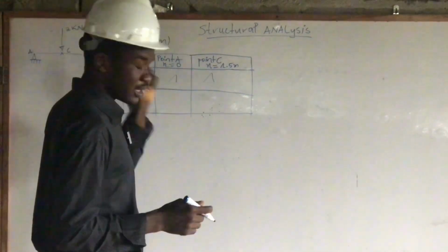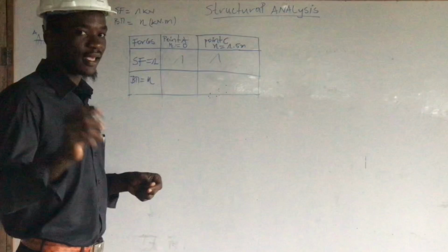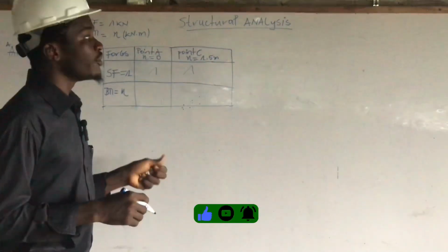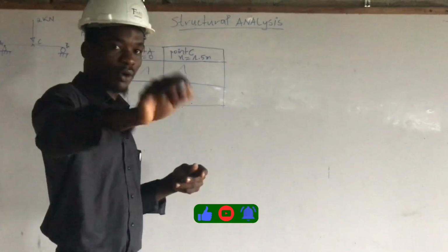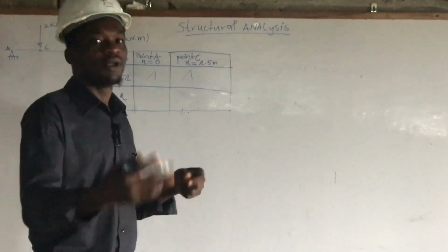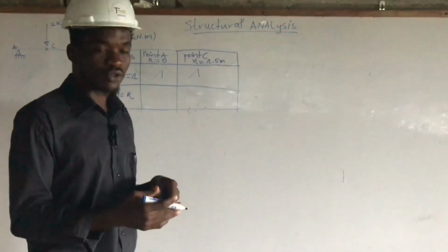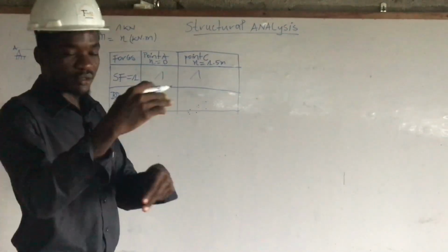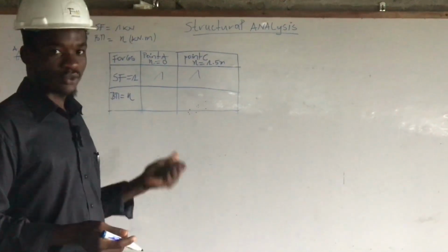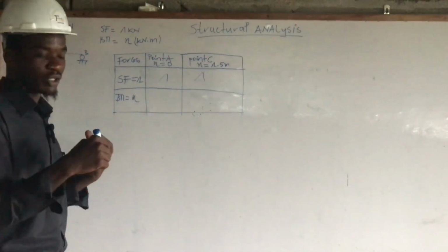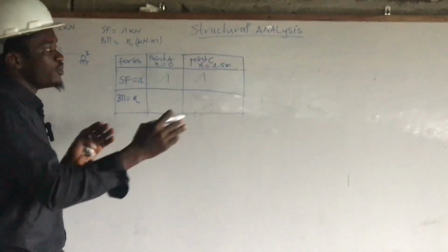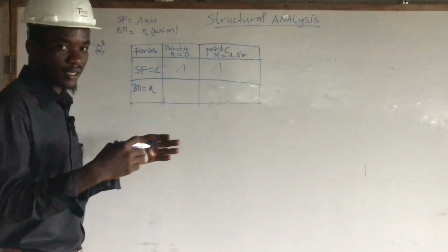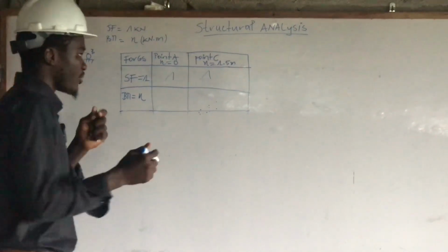Remember, this is the case of a concentrated load. Why are we ending here at 1.5? Because for the other side of the structure, we just have to repeat the behavior of the structure by making it go in the opposite direction to the first side where we made a cut, because the behavior of our structure will be the same on both sides, just in the opposite direction.